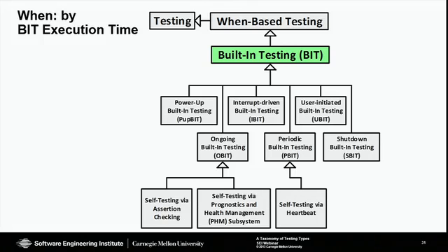You could have interrupt-driven built-in tests, where when a certain event occurs, the testing takes place. You can have periodic built-in tests, so every so many milliseconds or seconds or minutes, a test is run in the background. Heartbeat tests are performed this way. You can have the actual operator or user initiate a built-in test whenever they want, or when you power down the system, you can have built-in tests run there.